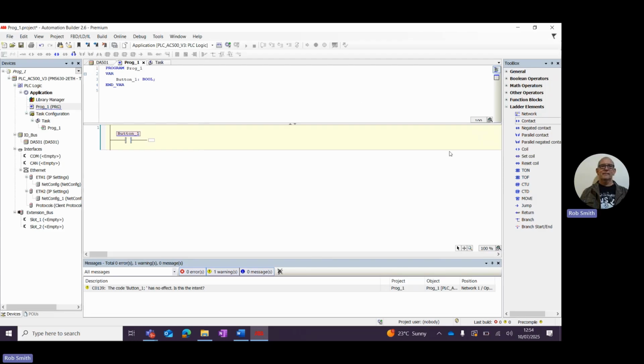Now we need to go to our output, and our outputs are generally coils. When you think of an output as a motor or a pump, or maybe an old incandescent bulb which had a coil that heated up to give out light, our output is going to be a coil. So I'm going to select my coil, drag it in. You can see you've got this no entry sign, but it does tell us where we should put it, and we'll put it in here.